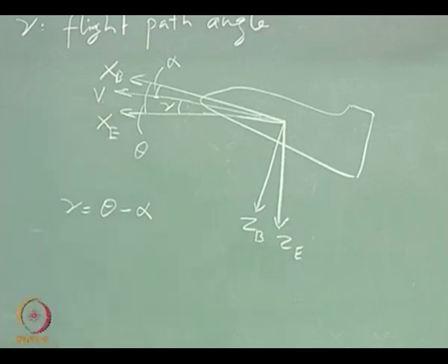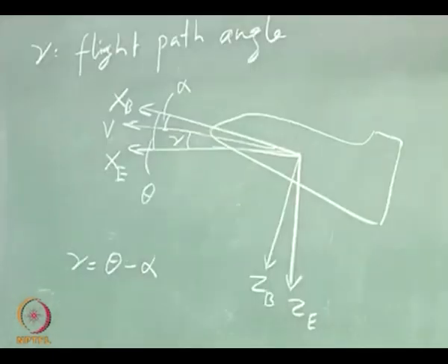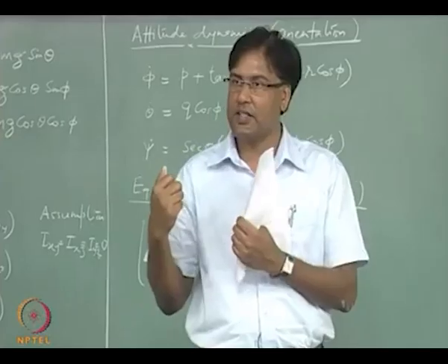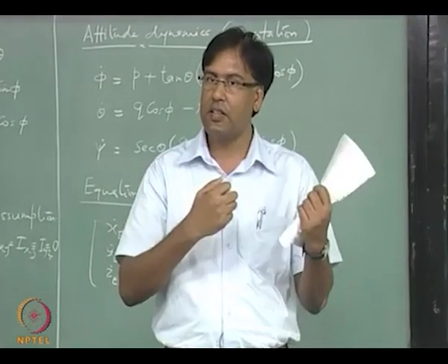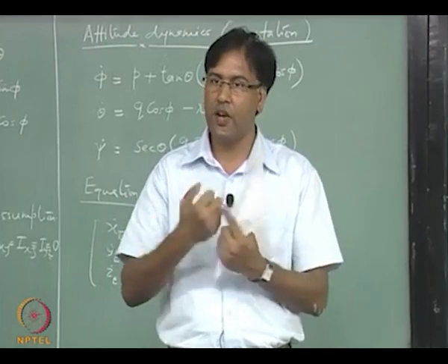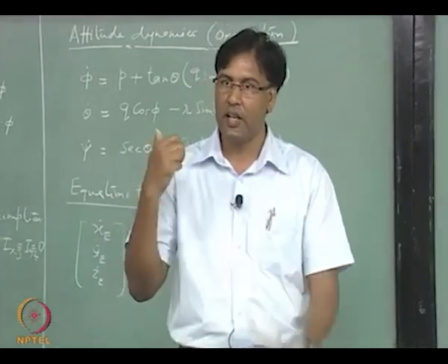Now, let us say my aircraft is having a velocity vector which is including angle of attack and side slip, right. It is not in 2D plane. Then you have to talk about 3 angles which will relate components of vectors in earth fixed axis system and the wind fixed axis system, right.